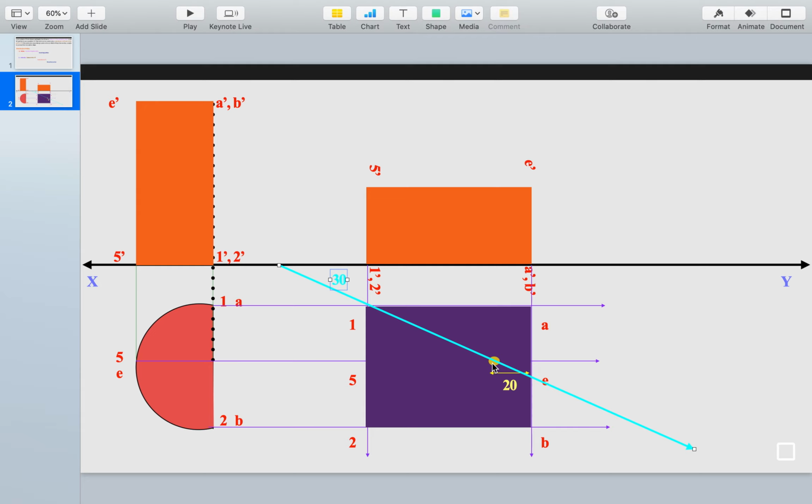Next, after drawing the section line, we have completed 50% of the work. The remaining 50% is giving the nomenclature. Wherever the section line cuts the lateral edge, we will name that point. Similarly P, Q, R; in your cases you may get more points. I have not drawn a middle line, so I will get only 3 points. Now once you have given the nomenclature, the position of P is understood, Q is understood, and R is understood.